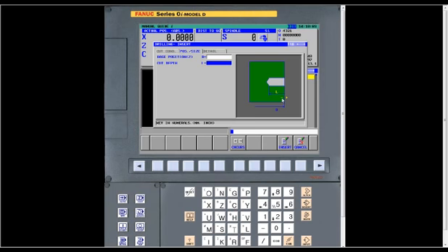So that's very simple. Then it also has detail data. And again, all four of these have asterisks next to them, so you do not always have to answer that information. But what this detail is, say you had a very large drill and you wanted to start it out at a much slower feed rate than what you would actually want once it got fully engaged. That's what this is for, where you can start out at a slower feed rate and then increasingly make it faster. So that's what a drill cycle looks like.